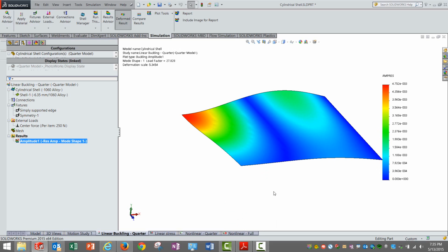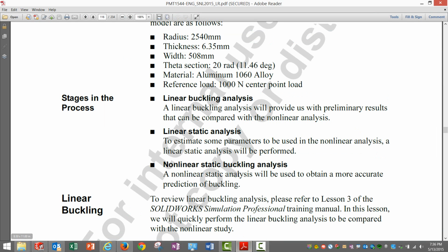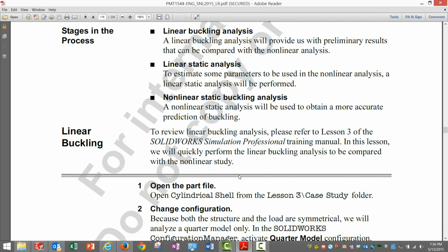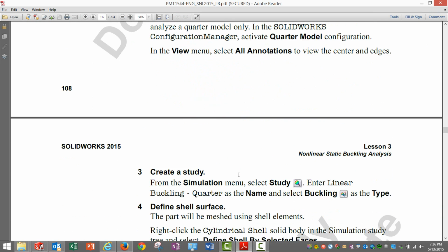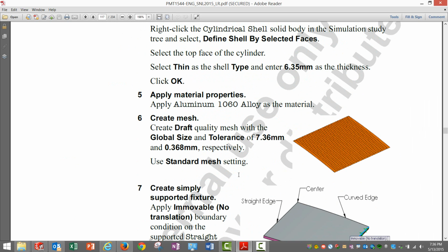We are going to discuss this in more detail, wherein we talk about whether symmetricity is making a difference, whether to use symmetric models for buckling analysis, and why. But at this moment, you can realize that this particular model is a quarter symmetry model. Number two, the loading is absolutely at the central point, so it's okay to use symmetry. However, remember the result. We'll discuss more in detail in this topic, but that's what it is. We got a multiplication factor of 27.